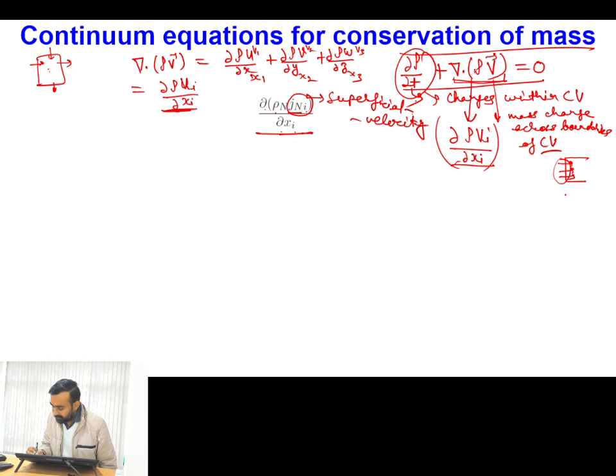But in case of multi-phase flow, what will be happening? At this boundary, there can be a situation that along with the continuous phase, some bubbles are also entering. So it means that over this entire area, phase velocity is not applicable. Phase velocity will be only applicable at the corresponding locations. But which velocity is there which we define based on the total area? The velocity which we define based on the total area for a particular phase is known as superficial velocity.